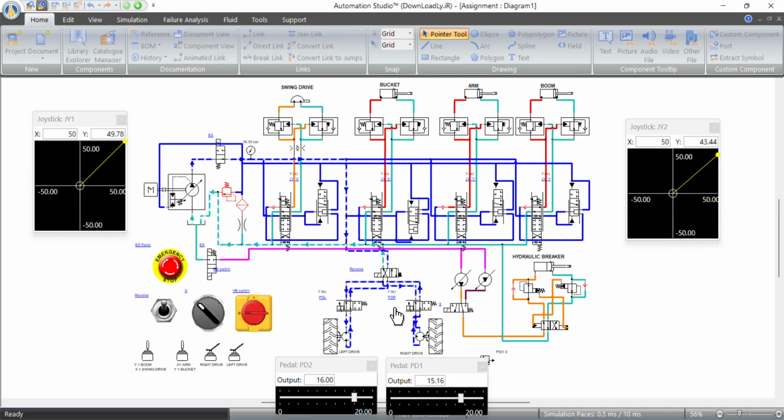When the fluid passes through the check valve, the pressure of retraction increases until a maximum pressure. Then the pivot of the valve will actuate the 4/2-way DCV to switch the direction of the flow. The flow of extension is then similar to the retraction as well.